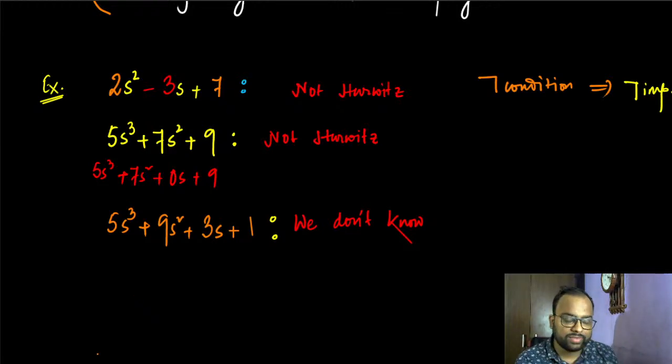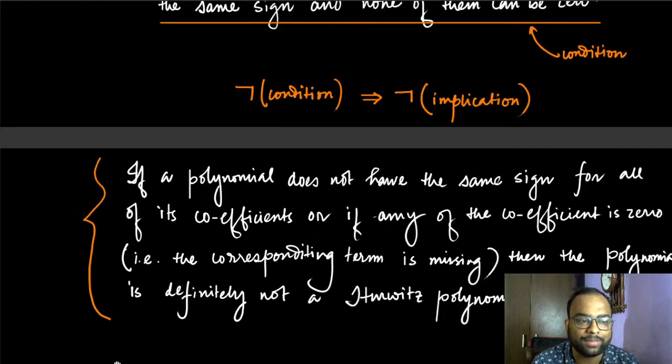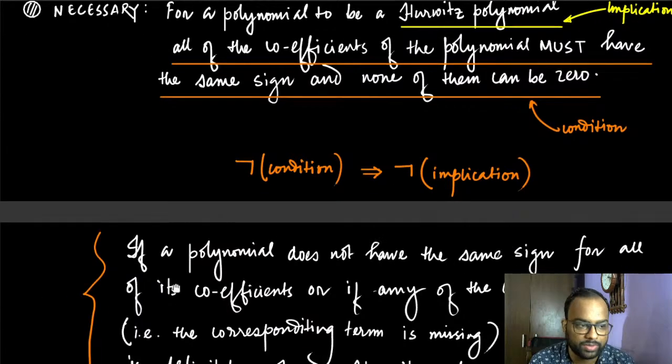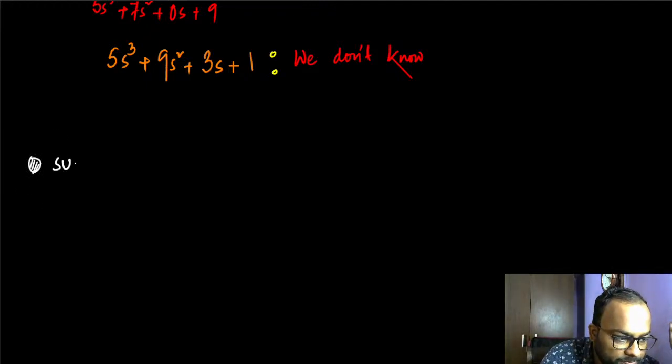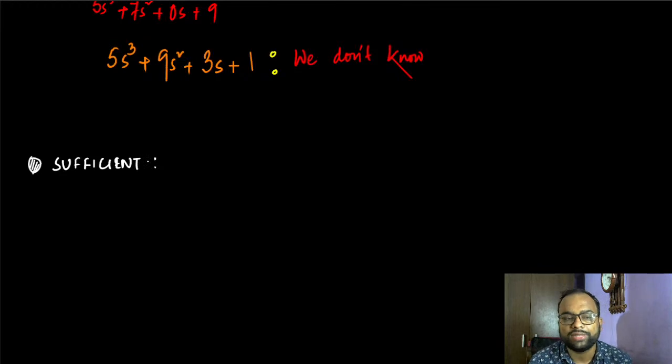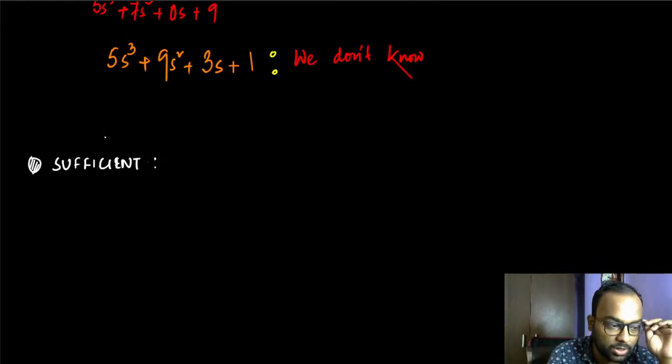So if we are there, then we have to construct something called the Routh table, and check for something else as the sufficient condition. Again, we are going to explain what a sufficient condition really means, but just hold on. Sufficient conditions are those kinds of conditions where, if this is satisfied, then it is definitely a Hurwitz polynomial. Okay, just let me write it down. Sufficient condition.